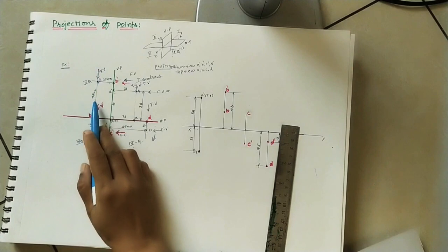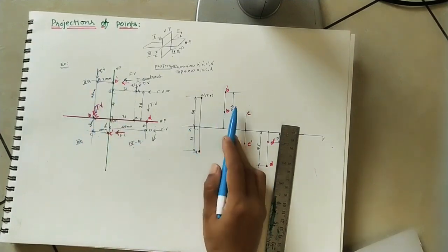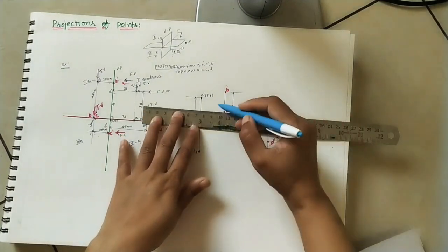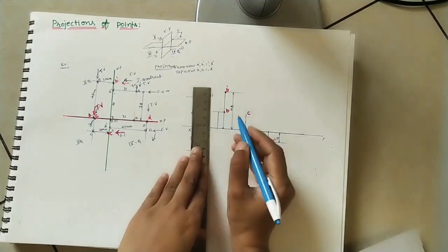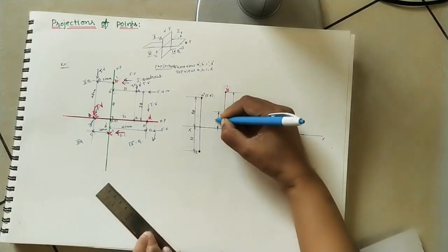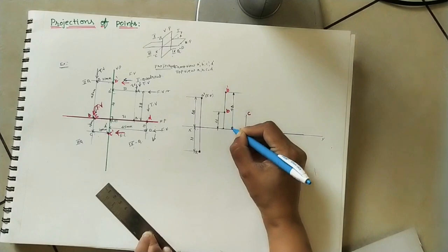And where is the top view? Top view is 21 mm. Okay, so mark the smaller dimension this side. One side is bigger dimension, one side is smaller dimension. This is the 21 mm. And instead of keeping arrows, fill these arrows. The thickness should be less.